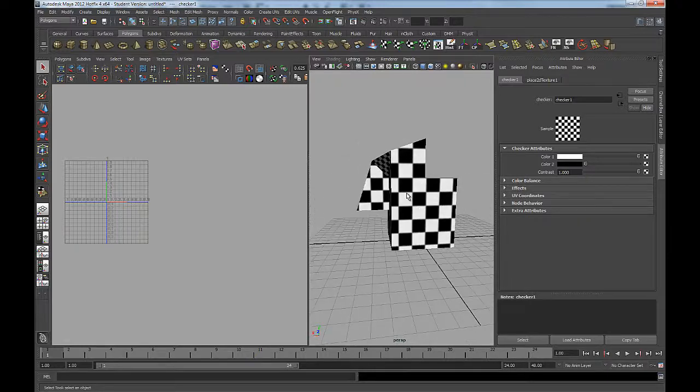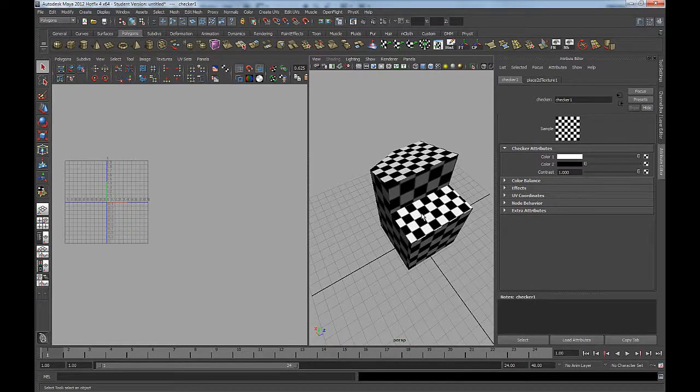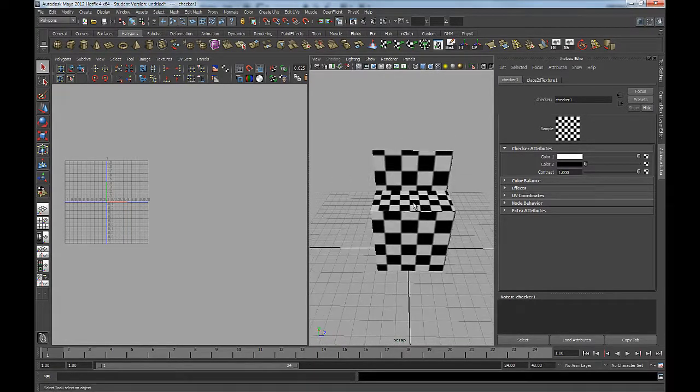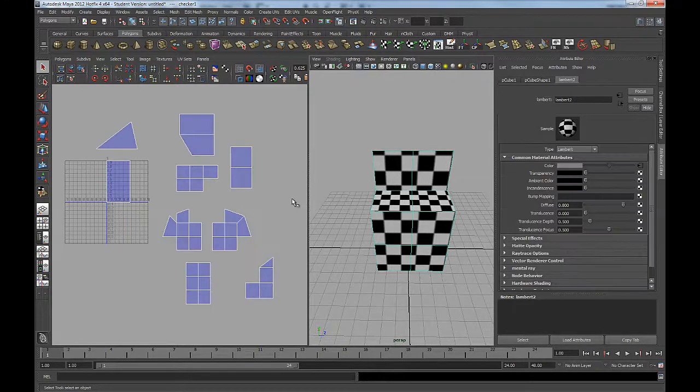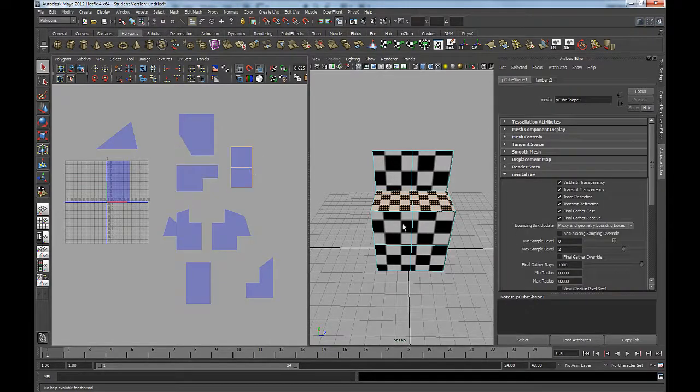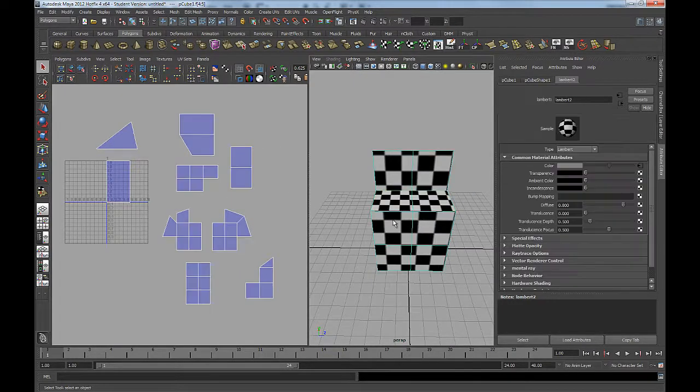So you can see some of these panels have bigger squares than others. So these ones here are pretty small compared with these. In fact, these ones are almost half the size of these. Okay, so what that means is when the squares are smaller, it means those polygons on the template are too big. All right. So for example, these two polygons here are these two. Okay, I can select those. You can see that they highlight. These two polygons basically should be the same size as these two, which are sort of here. So these are actually twice the size, almost.